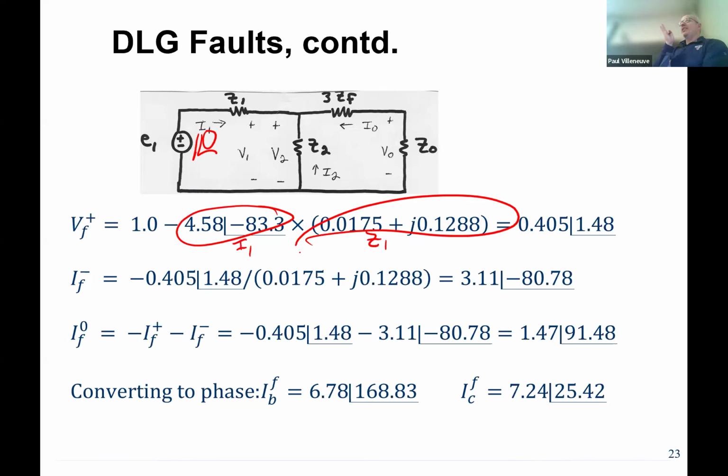So they're not particularly complicated circuits to do circuit analysis on, right? I mean, this is a pretty simplistic circuit. The problem is if you go to a system that is incredibly complex, with maybe 50,000 components, and then breaking them down into very simple diagrams. But that's what the programs do when you're calculating fault currents. They build Y bus, they invert and get Z bus, and then they have the Thevenin equivalent impedance seen at every bus. This is for a balanced system.